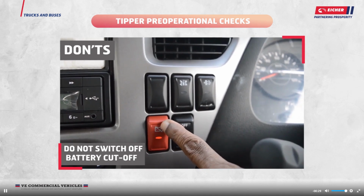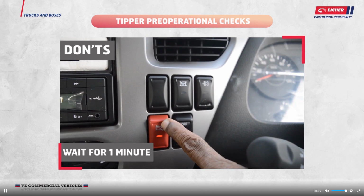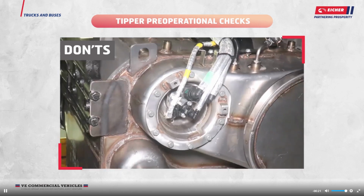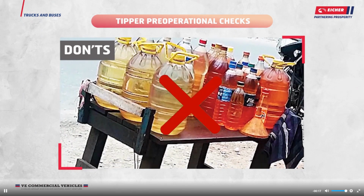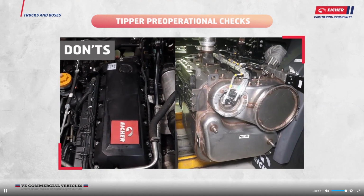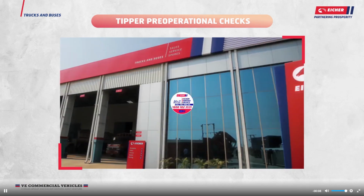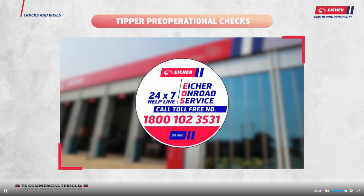Do not switch off the battery cutoff switch immediately after the ignition is switched off. Wait at least for 1 minute to avoid AdBlue crystallization in the system. Do not use adulterated fuel. Usage of adulterated fuel leads to damage of the engine and after-treatment system. Visit the nearest EICHER authorized service center or call EICHER on-road service for any further assistance.